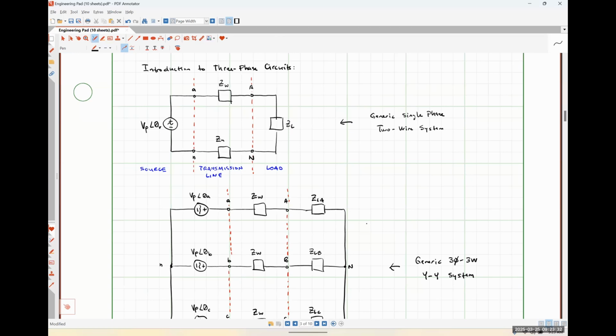In a three-phase system, we'll see this here probably by the end of next week, the power that is delivered to these three-phase machines is going to be constant, which means they're going to generate a constant torque. And so those machines are going to last for a really long time because they experience the smallest amount of vibration that we could expect of them. So there's going to be significantly less mechanical wear and tear on a three-phase motor than there will be on a single-phase motor because the torque it generates is constant. So that's why three-phase systems are used in so many industrial settings.